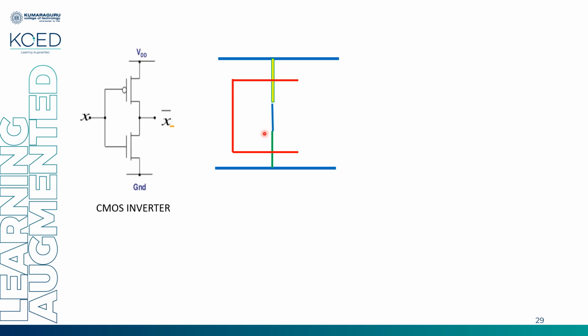Connect the drains of both your NMOS and PMOS with the help of a metal. Take the output, and the input is given. Now VDD, ground. VDD and ground are represented as the cross mark. Now establish all your electrical connections.